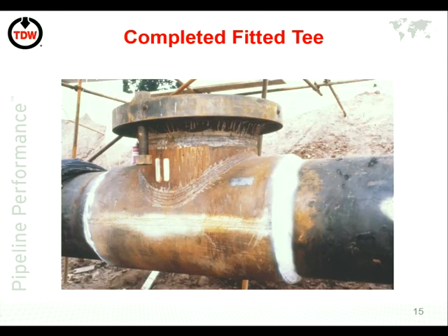No, I understand this one. Can I show you? I cannot explain. No, I understand that this is welded as well. I mean here, inside of this part, that it's isolated. It doesn't have to be. There can be a void in here. It doesn't matter. It doesn't have to be a neat fit. It's not the sealing element of the fitting. So the product can go there. Yes. The sealing element of the fitting is this weld. Well, these two welds and this weld here. What goes on inside is not too critical. It can be lived with.